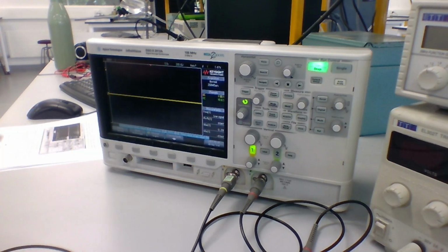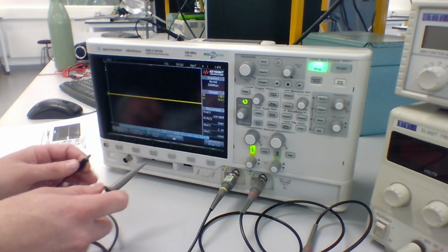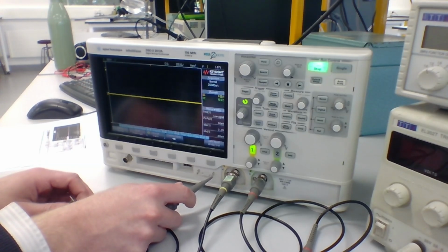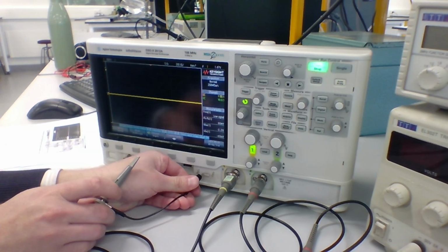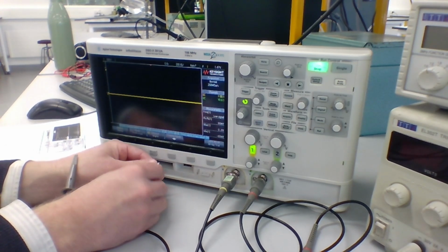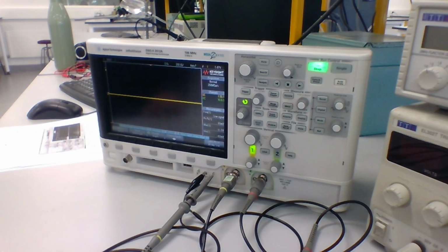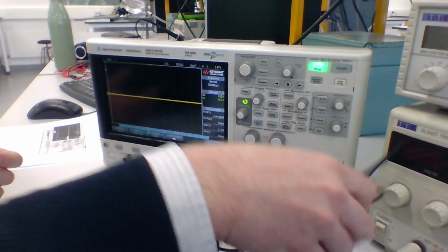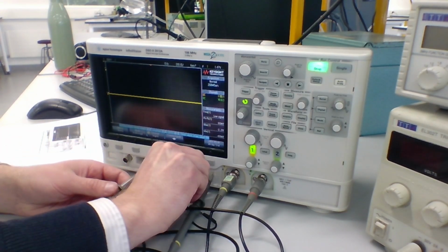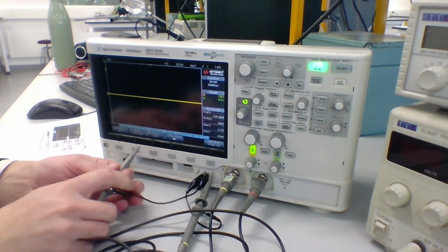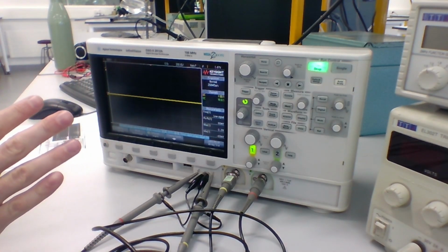What we're then going to do is take one of these oscilloscope probes, and we're going to connect the clip here to the little hook here labeled Demo 1, and the ground clip to the middle ground hook on the oscilloscope here. You'll see it's got a little ground marking underneath it. So pull that back and hook that through. We're going to do the same thing with the other oscilloscope probe. We're going to ground that and connect that to the one that's labeled Demo 2. It also has the label Probe Comp underneath it, which we'll look at in one of the later labs. Okay, so we've hooked both of those up.